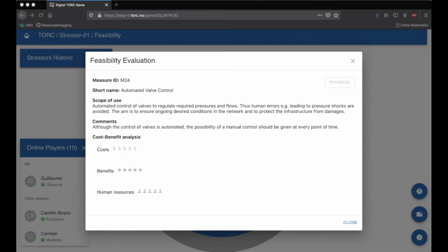Okay, somebody suggested automated valve control, so I would like to understand why this choice. So you can act quicker to isolate the pipe with the leak. Yes, so you are referring to when, for example, you want to repair the leak. Then, if you have an automated valve control, you can do it faster. That's what you mean? Yes, and to supply these affected people